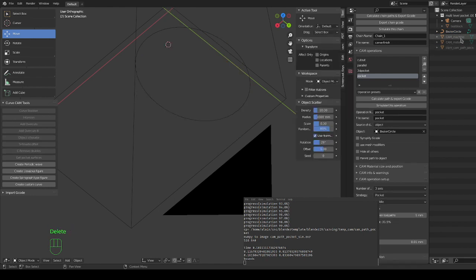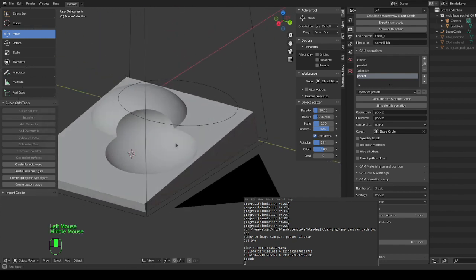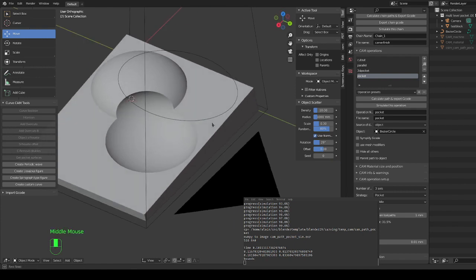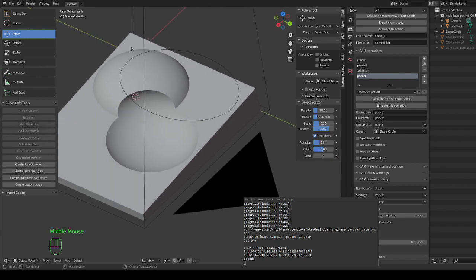And what if I want to make a pocket but make it collide with my test block of earlier? Well, I don't really want to make a limit curve. We could do that. I want the pocket pattern, because the pocket pattern goes around my curve and the edges are all going to be clean.